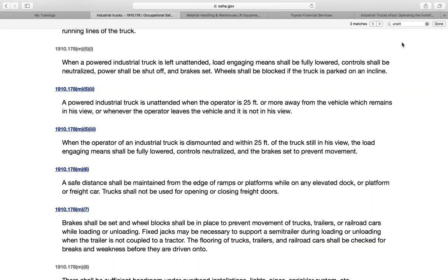Yeah, okay, good. So a couple of you have, huh? Yeah, and that's what they'll do. They'll go ahead, even with those narrow aisles, because if they accidentally bump the storage racks, it could be possible that something could fall, and it could also be possible that we collapse them, right? So we need to make sure that at least in the adjacent aisles, the parallel aisles next to it, we also control that area as well. Okay, good. So, and then let's talk a little bit about general guidelines, right?